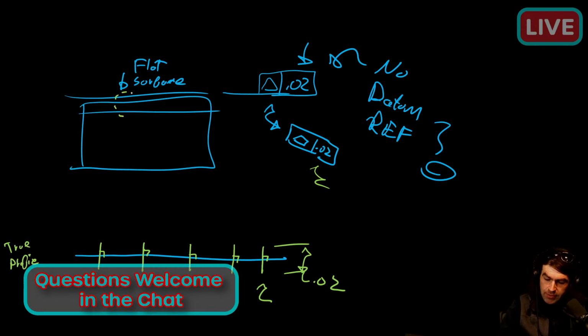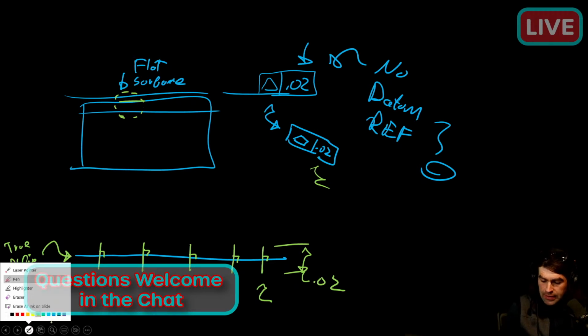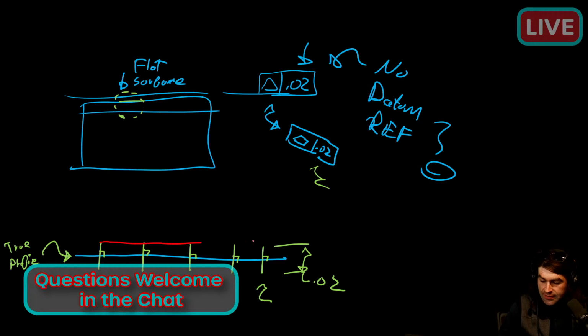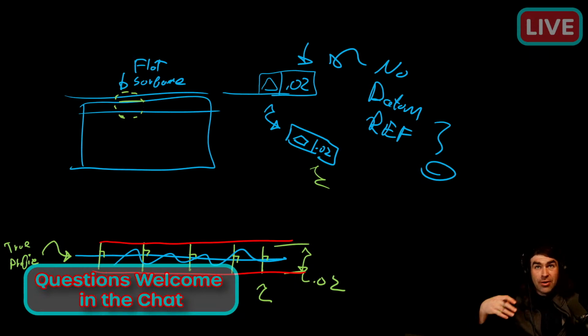right? And let's say we're just looking at this surface right here. This is our true profile. Those little lines are centered on the true profile. They're perpendicular to it. And now we connect all these little dots, and that's our tolerance zone, right? So the actual surface needs to be within there. So functionally, it's the same thing as having two parallel planes. It's three-dimensional. I said line, but it is three-dimensional with profile of a surface.